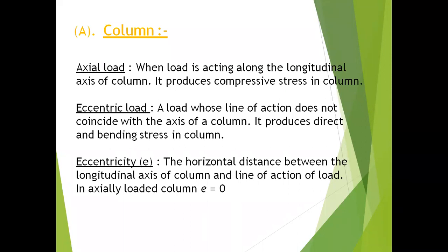Okay, inka, a jib of a crane, right? A crane has a boom, right? So that boom is also a compression member. So like that there are many compression members. Okay, so when a load is acting along the longitudinal axis of a column, it produces compression stresses in the column. That is what an axial load is.